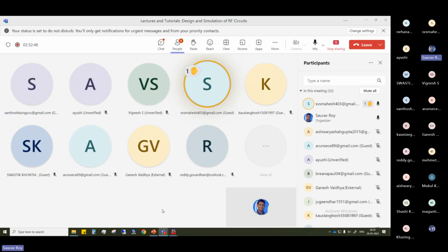Generally, that also is an option, but there are other better options available. Like the input divider, and as I told, the Gysel power divider. There are many different kinds of options. That will not require multiple branches like that. I mean, multiple branches obviously will be there at the output end, but if you just stack them like that, they will not be very efficient. Okay.